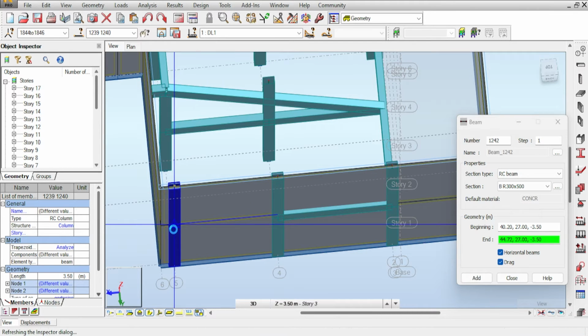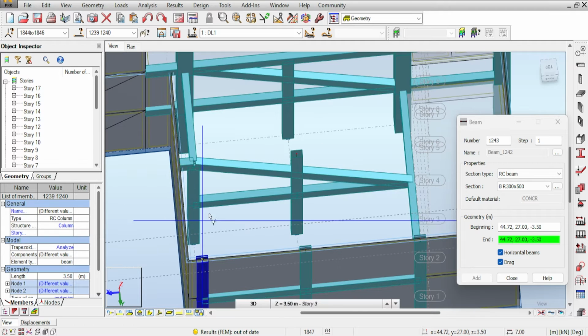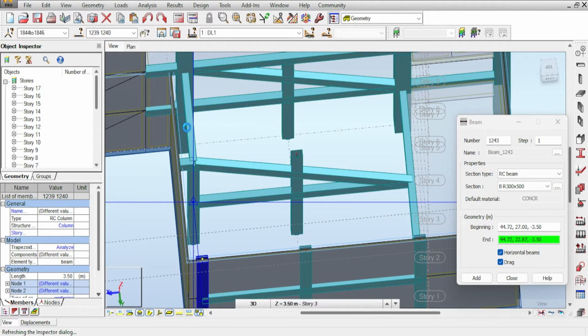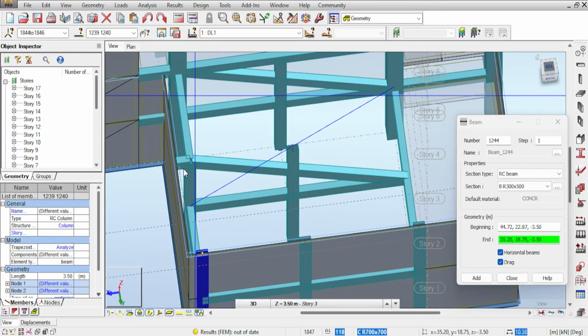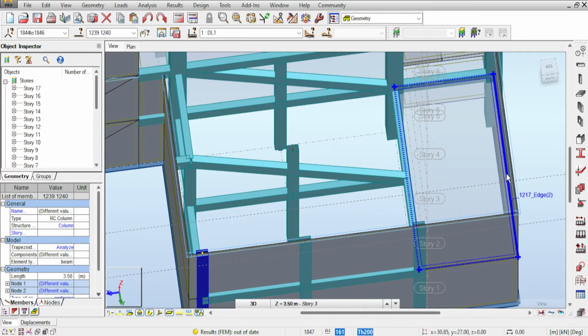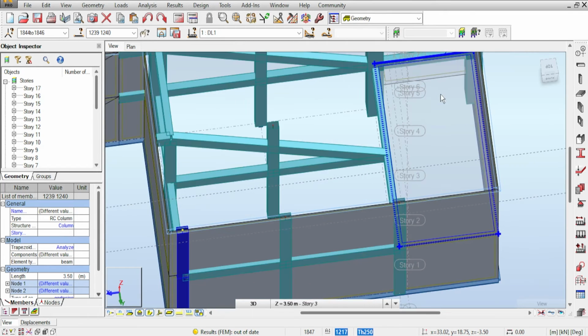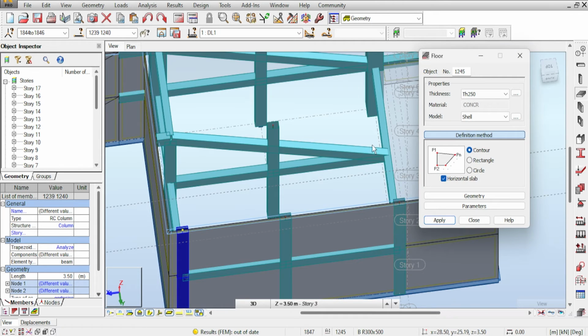and continue drawing that beam, and then draw the transversal beam here, because the landing, it's not called a landing, but this horizontal part of the ramp needs to be carried somehow. So I will carry it with the beam. I don't want to carry it on the retaining wall. You could carry it on the retaining wall. Once again, those are two possibilities you could have. And yeah, that's it. Now I will have to do my inclined slab and my horizontal slab.